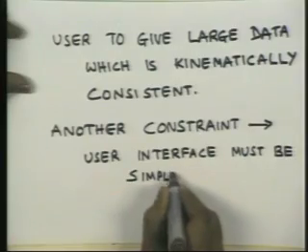That is, we don't have to give complicated expressions, functions of time, for the specification of the task, which is in world coordinates as he sees it as a user. Okay, he should be able to specify the task that needs to be done in a simple manner. That also throws light on the fact that for many of the intermediate via points, he doesn't really care that the end effector tip pass exactly through those points. It could be approximately there, or even if it passes exactly through those points, he may not worry about the velocity with which the end effector tip moves through them.